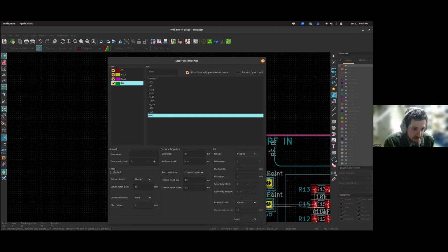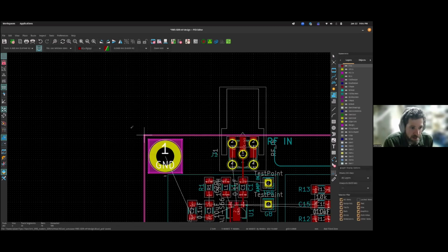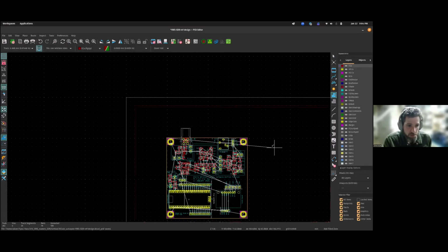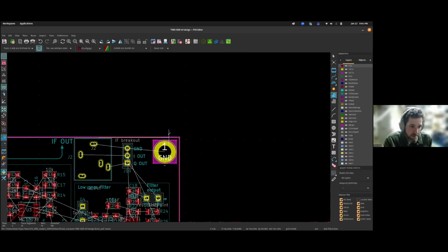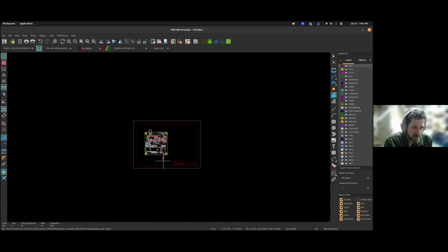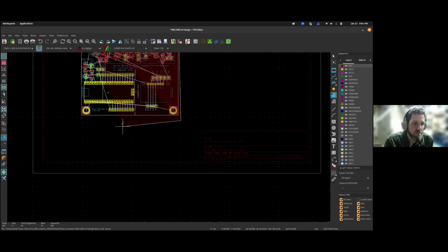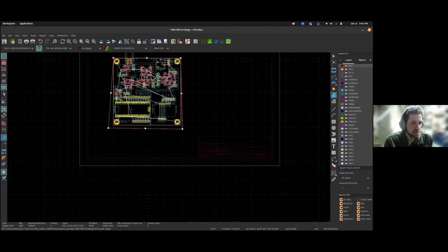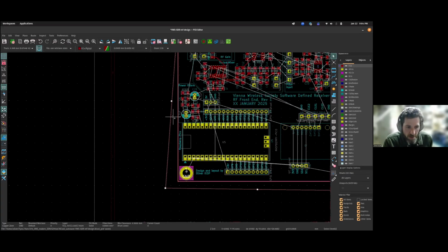So now it's going to make this a ground plane on all 4 layers of the PCB, that it will fill in automatically. Okay, now I can continue, zoom out, scrolling the center mouse button, zoom in again to hit the other vertex. You don't have to be precise. I could be off the PCB like this. It just looks neater if it's precise. And then the last vertex, you double click. So now it has filled out. It's now got this rule area that it's added here.